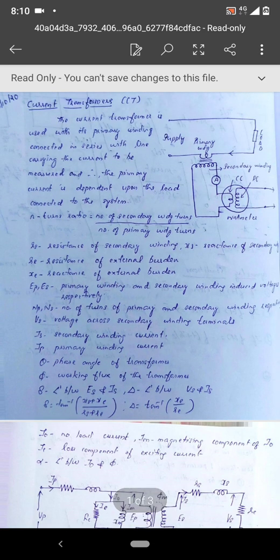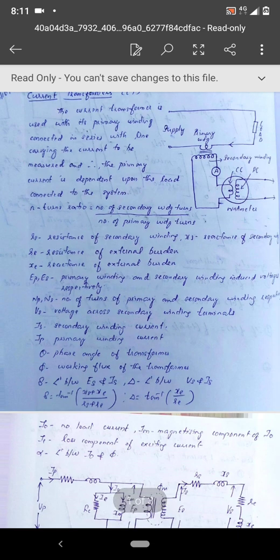So whatever I told in words is expressed in the figure there. You have the actual circuit, so that conductor will itself act as the primary winding. Only one or a few turns are there, and the secondary winding has more turns than the primary. And in the secondary circuit, you have an ammeter, or both an ammeter and the current coil of a wattmeter. So the ranges of the current coil of the wattmeter and the ammeter are extended by the use of the current transformer there.